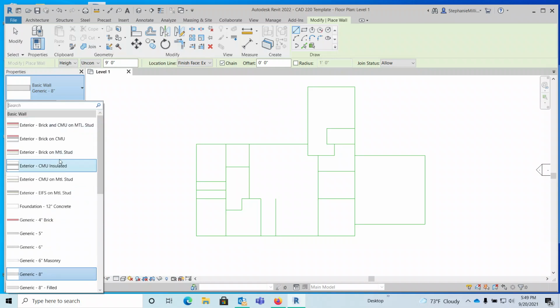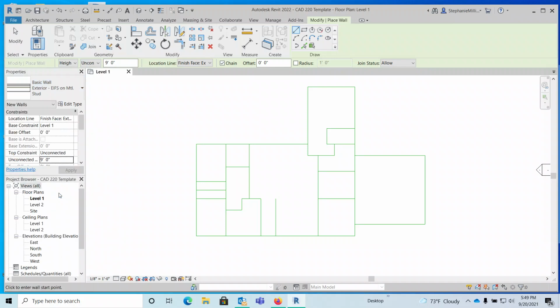So I'm going to go back up. I'm going to pick exterior. And another thing to note, I think I added this in some of my text materials in Blackboard, just to keep in mind: if you're drawing a foundation and you're also enrolled in the construction techniques class, the exterior wall, the outside edge of your stud, is always going to be aligned to the foundation exterior edge.